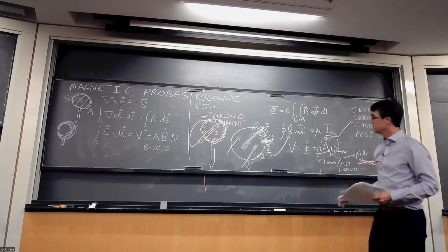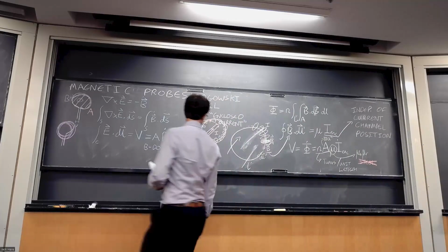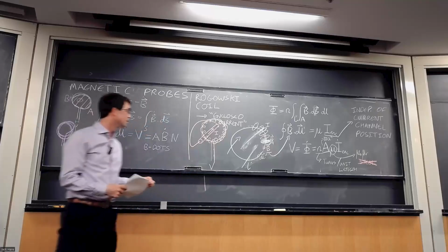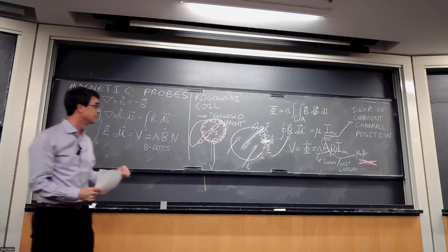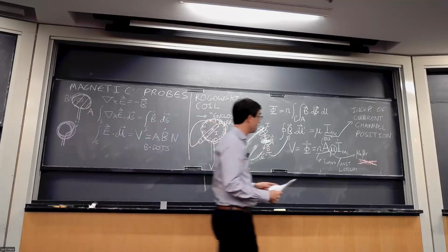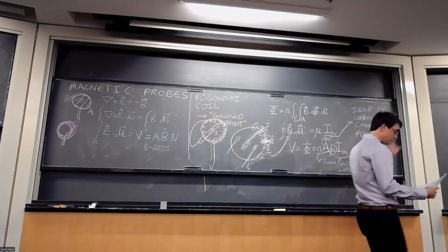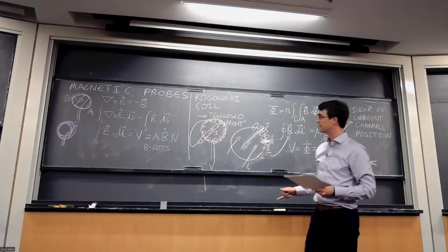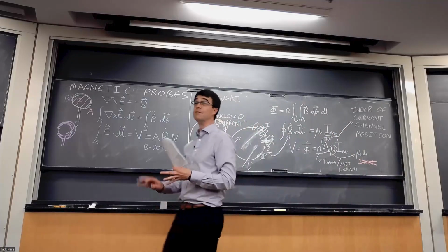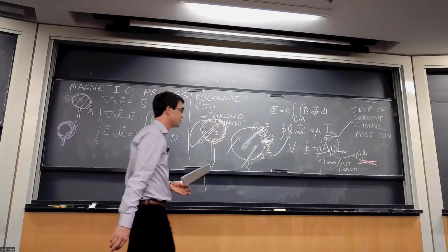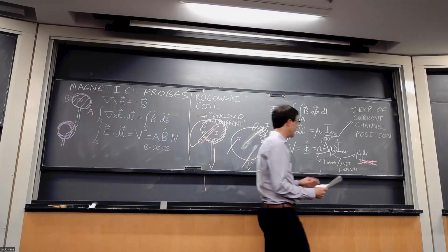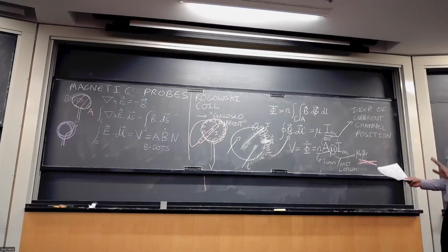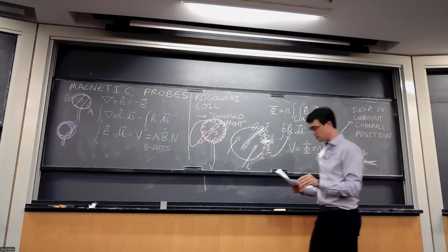Okay, and you can go and wind one of your own of these. You can strip back a BNC cable and get some magnet wire and wrap it all the way back around, which is what Thomas Varnish has been doing for Puffin experiments. Or you can go online and you can get something from Pearson. So everyone buys Pearsons. These are these nice green loops, and they have a passive integrator built into them, like we discussed before, and they're labeled in volts per amp. So if you just want something off the shelf and you've got lots of money, you can buy something like that. So these are absolute workhorses, not just for plasma physics. These are just if you want to measure current going through something.